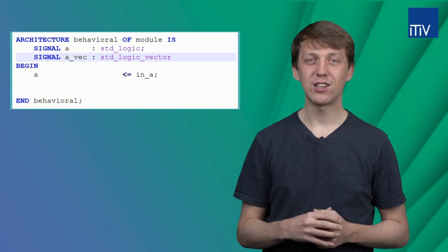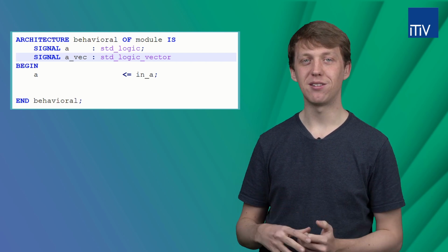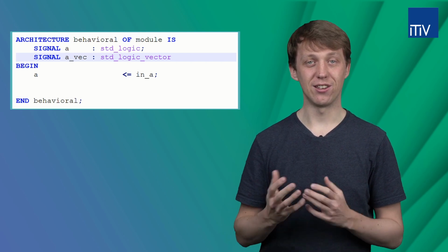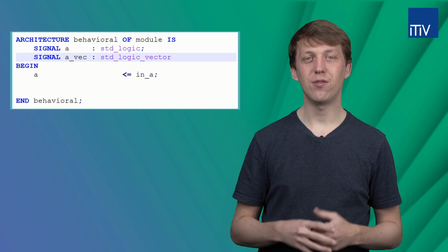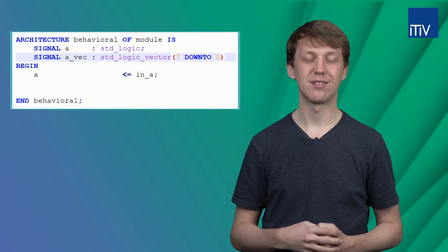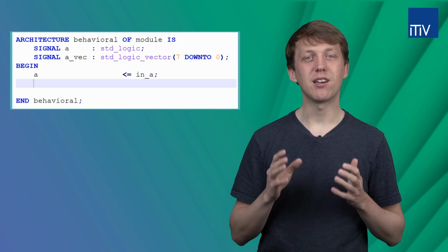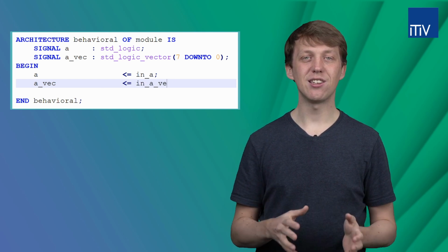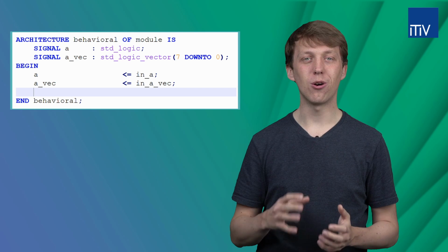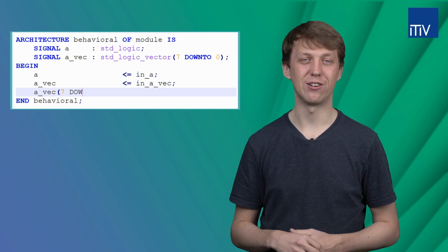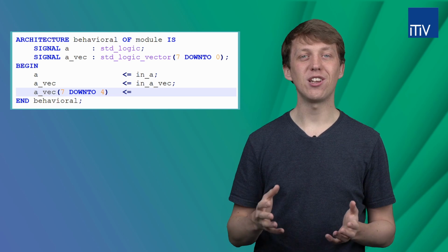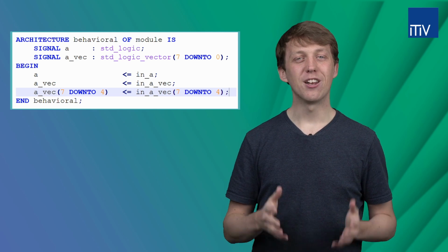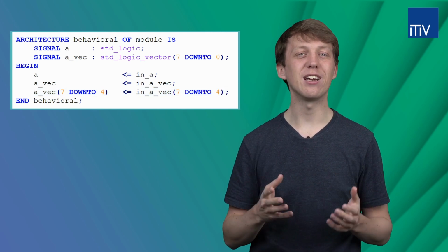Usually, the declaration starts with the most significant bit, the MSB. And since the array index starts at 0, we declare the size of the vector using 7 down to 0. The signal assignment can be done similarly to STD logic and bit. Additionally, STD logic vector also allows to only consider a subset of the vector. As an example, we can only consider the 4 MSBs in our logical function. Okay, cool. Now it's clear how to model signals using 9-valued logic.